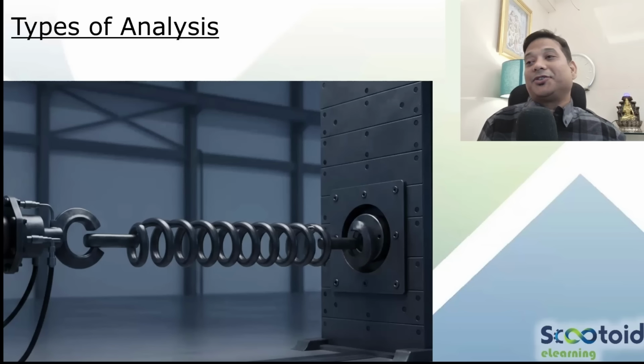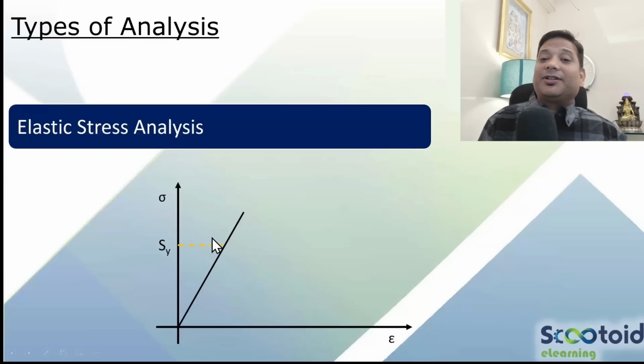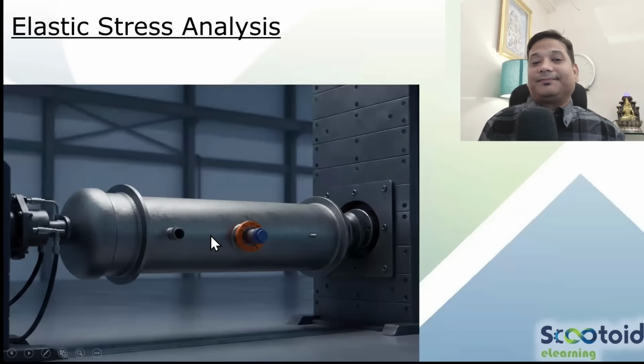What is the classification of that stress, which will be there in the round bar? It's primary membrane stress. What is the limit for primary membrane? It's the allowable of that particular code. If I'm using a round bar in tension, it is a very simple analysis. But will my pressure vessel also behave in the same way?